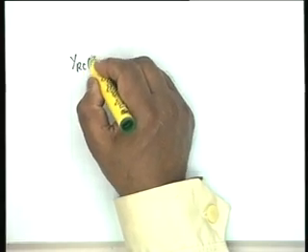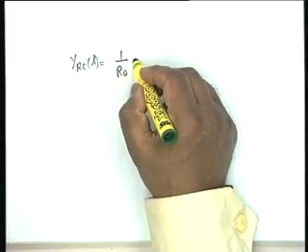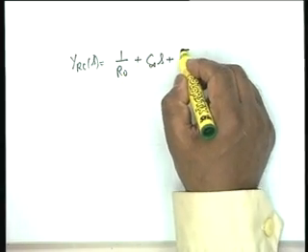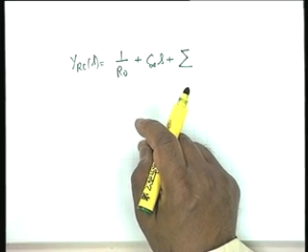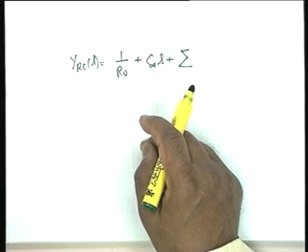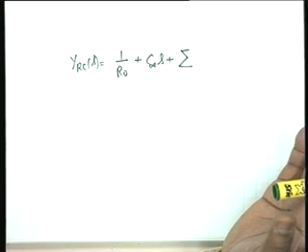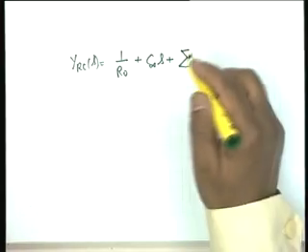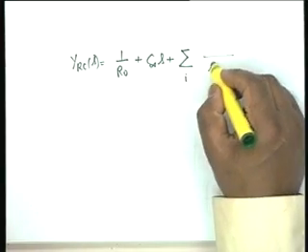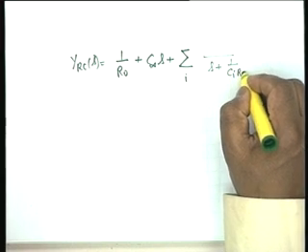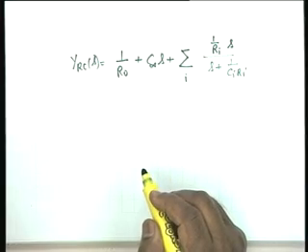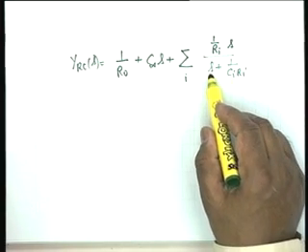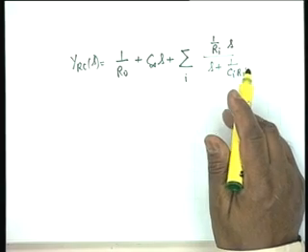Let's do a further bit of simplification. I must have your undivided attention, total attention, because things can become confusing. RC impedances do not have the same properties as RC admittances. Unlike LC, where you see ZLC and YLC have the same partial fraction expansion, it is not the case here. You see the difference. I can write this as S plus 1 over Ci Ri, and I can write this as 1 over Ri multiplied by S. Agree? I have written the denominator as a polynomial, the leading power of which is unity.